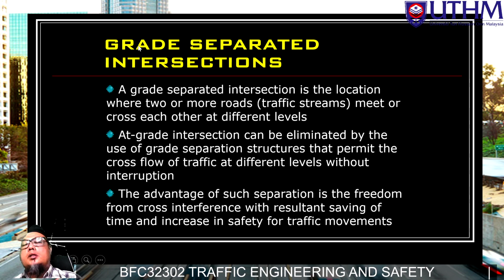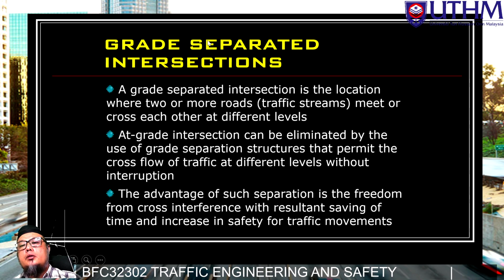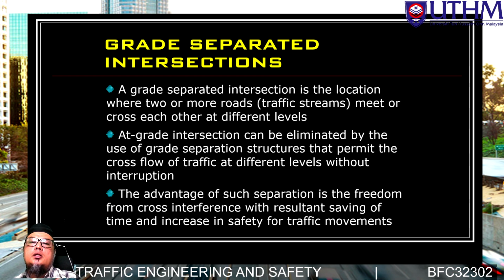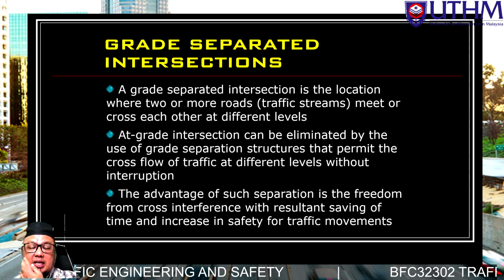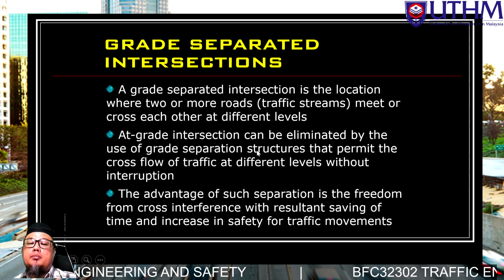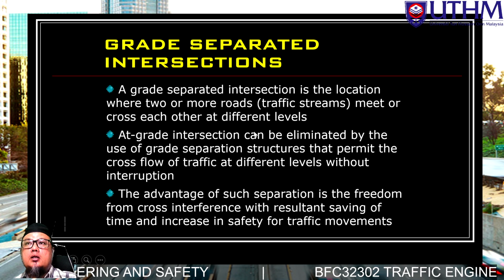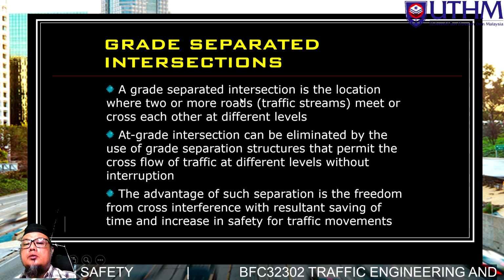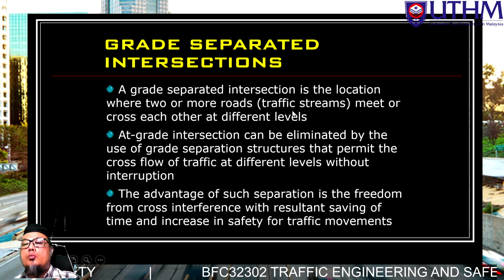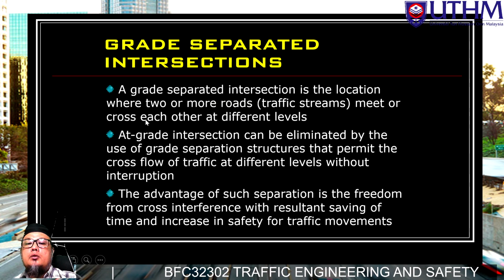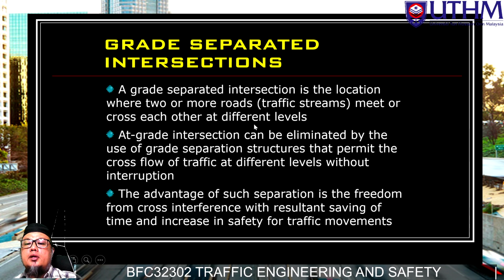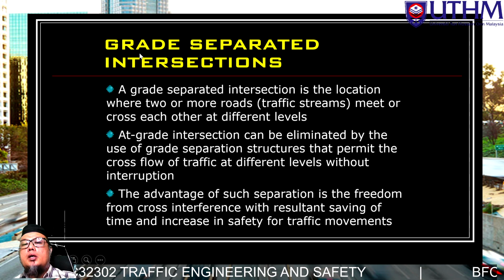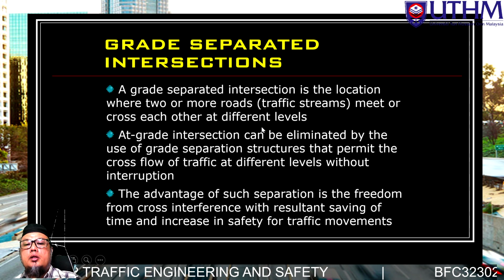Okay, next the type for grade separated or grade separation intersection. If we meet the term grade separated, actually they are interchanges, multi-level intersections, at different levels. Grade separation or grade separated intersections is the location where two or more road streams meet and cross each other at different levels. Notice this term, different level. At-grade is the same level, but grade separation has one below and one above.